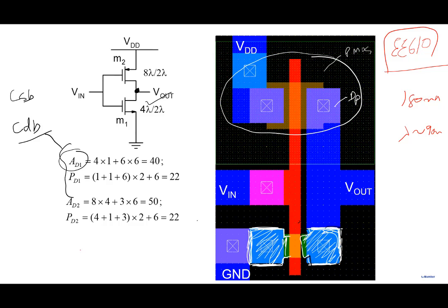All your delay calculations will be wrong without this, and I will show you some sample calculations. The drain to body capacitor is one of the most important capacitors there. Now, people who have not done the layout will use some formula for the area of the drain or perimeter of the drain and try to predict. You can say this is likely to be the area of the drain, this is likely to be the perimeter of the drain, and estimate a value. But it's very important that this information is available in some form, to calculate the values of the capacitors.